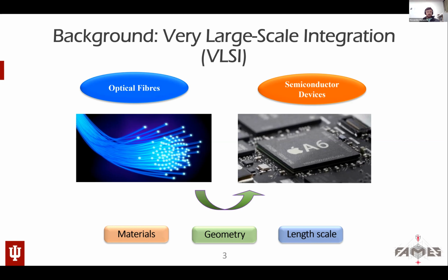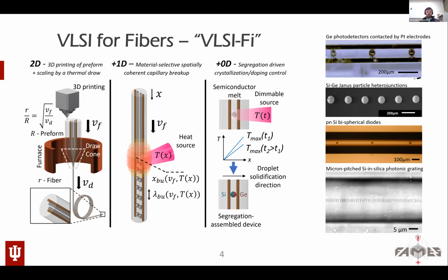And in this technology, there are ways to control the architecture of the microprocessor in all 3 dimensions. And we develop a control over the architecture of materials arrangements inside the fiber in all 3 dimensions. So we start with 3D printing the cladding of the fiber preform. That's the glass that provides the matrix of the structure.